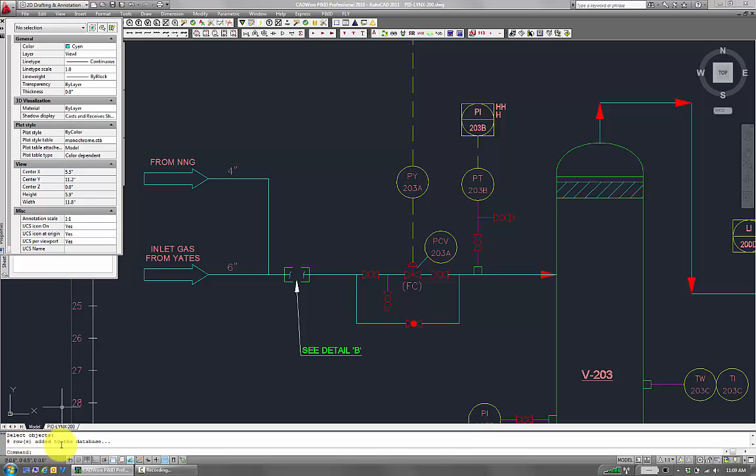So look, every one is a separate line in the database? So right now it's at 8 rows added to the database, but actually this would be one run. This would be one line, line number one ISO. Okay. So to make that one line in your database, you come back and you do your combine line. You select those segments as well. I'm going to do window select here. And what this is essentially doing is taking these 8 as well as that one row and deleting 8 out of the database and making one row for one line. And you'll see your command line is going to tell you exactly what it's doing. It removed 8 rows from the line table.